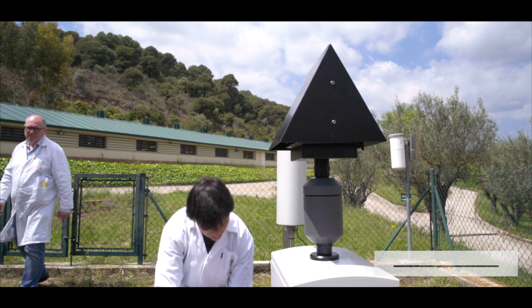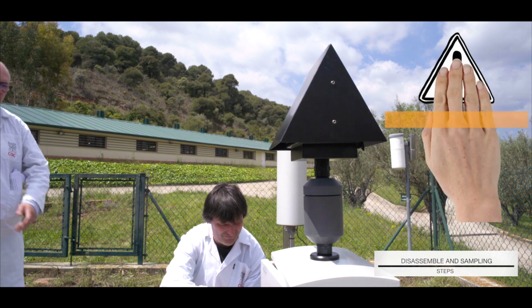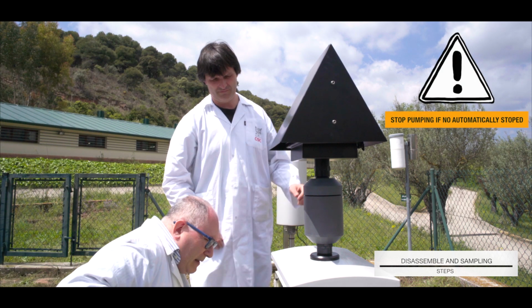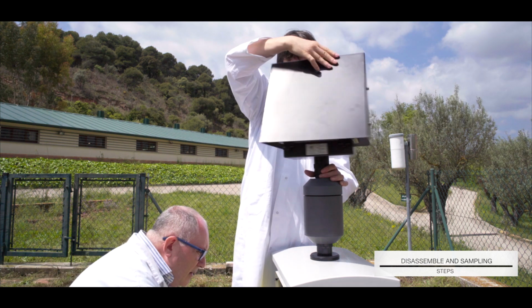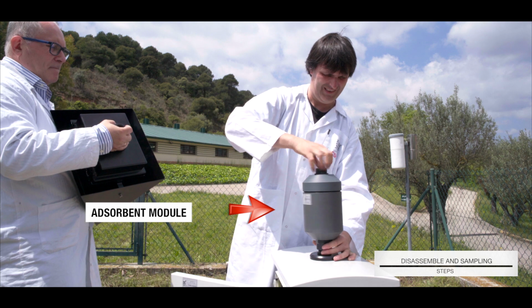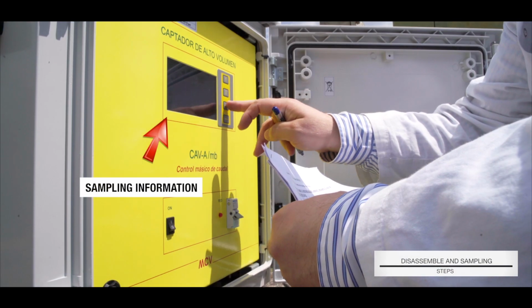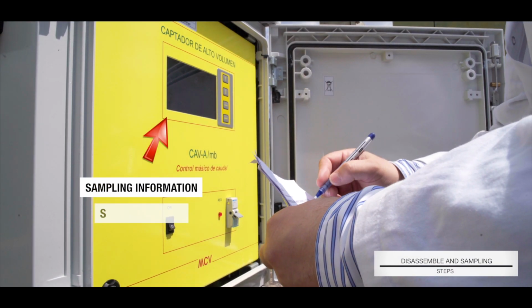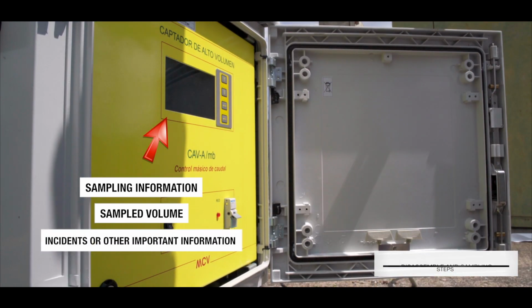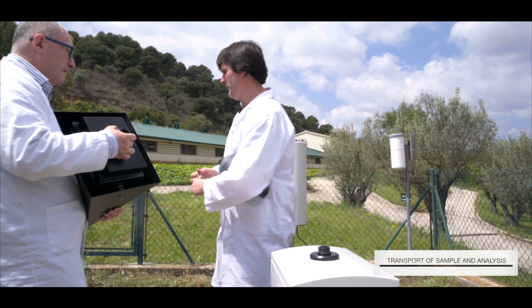When sampling is finished, we will make sure that the sampling device is not pumping. If this is not the case, the pump must be manually interrupted. Next step is to disassemble the filter, as well as the adsorbent modules, and to take note of the collection data, including sampled volume, as well as any incident that may have occurred. Finally, the sample must be sent to the laboratory to proceed with the analysis.